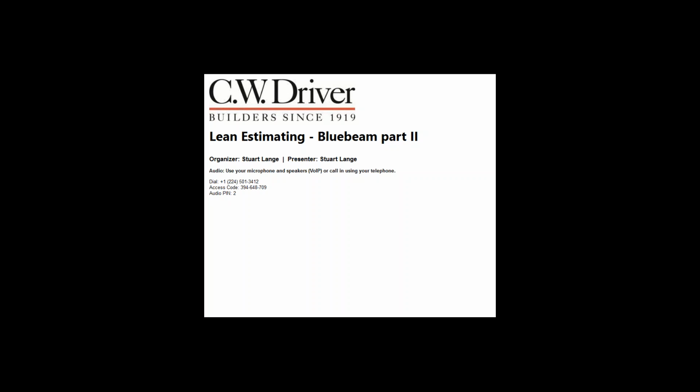So it's just a hyperlink to open a document instead of a hyperlink to jump to a place in a document. So if you had a huge file, and this is actually what they do in the field, they use each page as its own sheet. Each sheet is its own file. Because on iPads, to load up 200 meg takes forever. So instead, you can just open up the files that you need and then just link and open up that one little file. So you're opening lots of little files instead of 1 mega file.